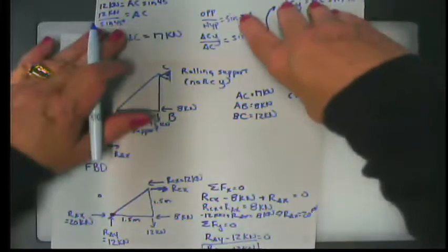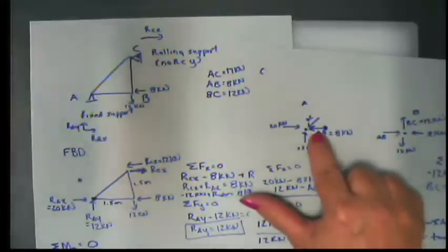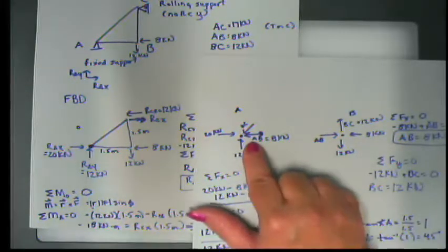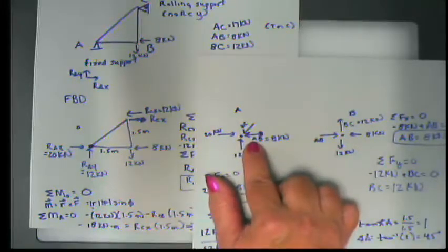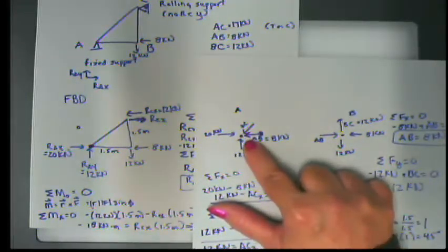So to do that, I go back to the joint, and I decide, are we pulling or pushing? Sorry, yeah? Is it just observational for the tension or compression? Sorry? Is it observational? Oh, right. We're going to look for the question, is it pulling or pushing on the joint? Yeah, absolutely. Absolutely observational. No more math. Good question. Okay, so what's AB doing? Is it pulling or pushing? Pushing, yeah? So that's in compression.